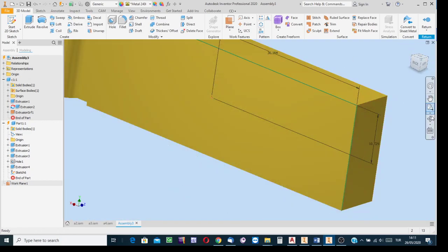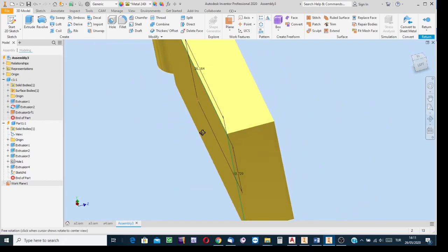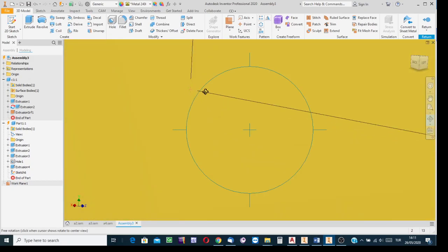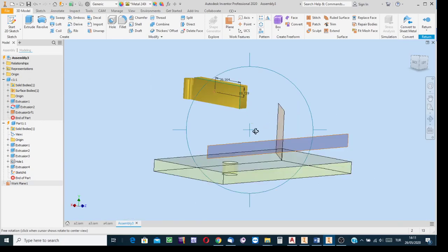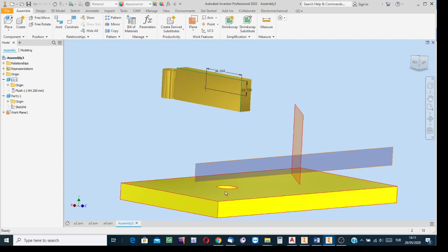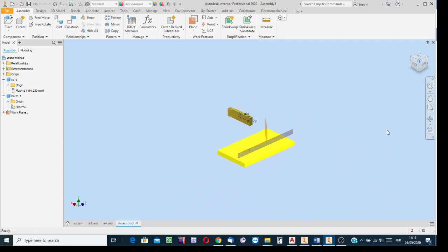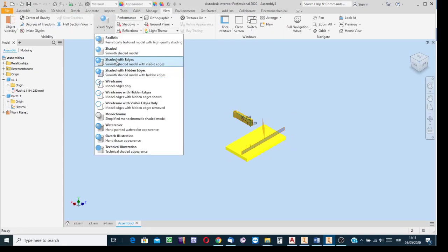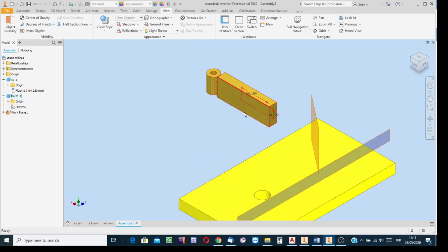Axis is not so distinguishable. In the simulation it is tiny, but yeah, it is over there. It is defined. Okay, and then return, and then see the rest. For instance, this yellowish one has a hole, and for the hole, the axis is defined. But if there were no hole, then similarly, I would use a work axis.